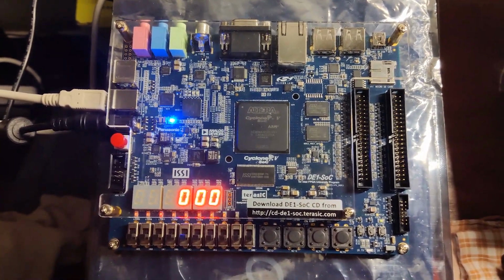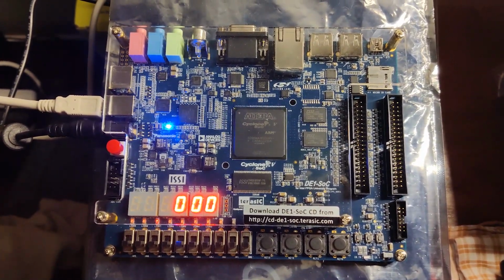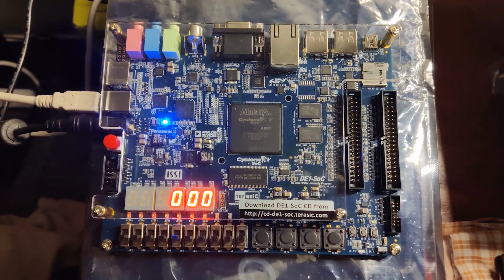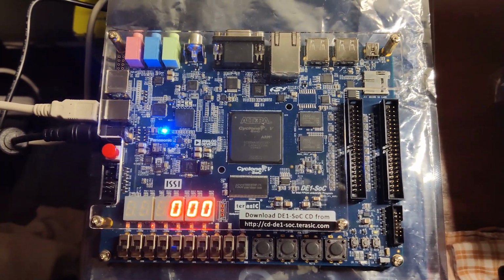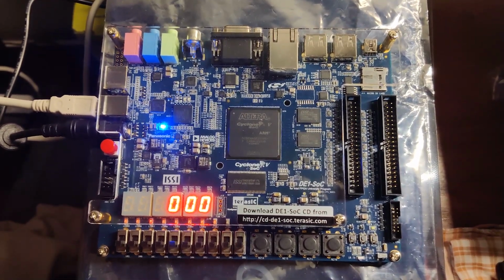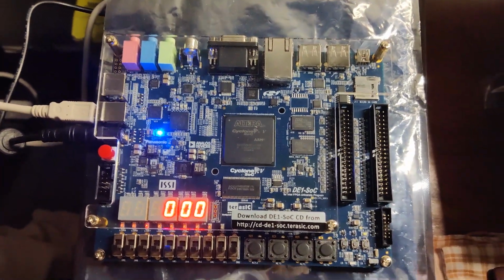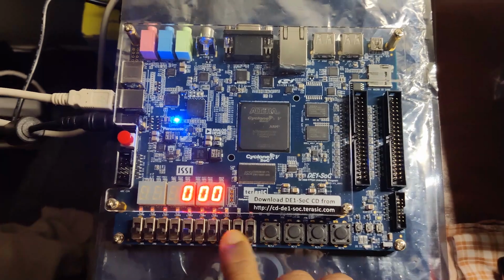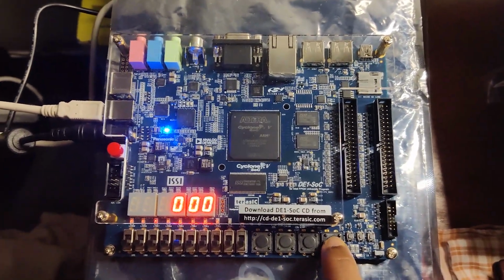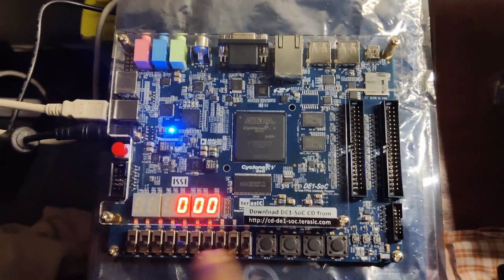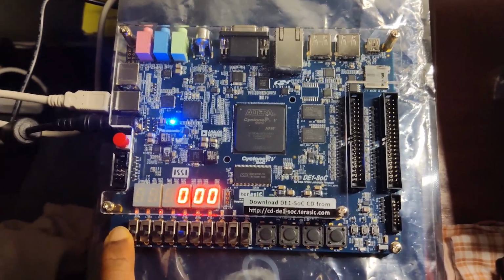I've used the Quartus Prime application to generate the bit stream, where I've followed the same steps as previous videos, where for the respective RTL based on its input and output, I've assigned its respective pins. Here I've assigned the first 8 switches as the 8-bit input, the first push button as the key value, and the last switch as the reset button.